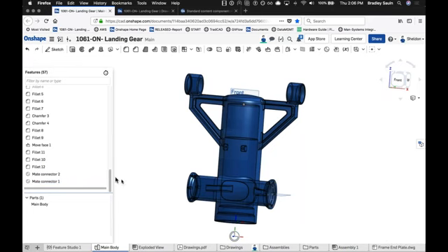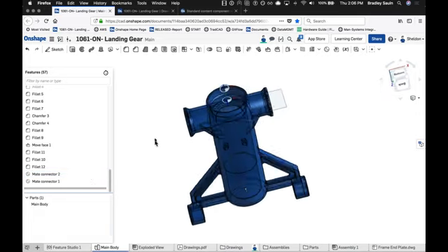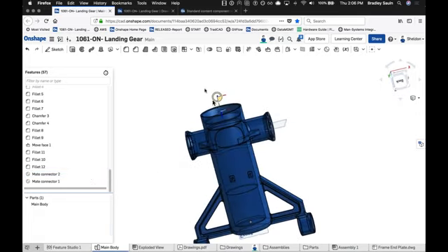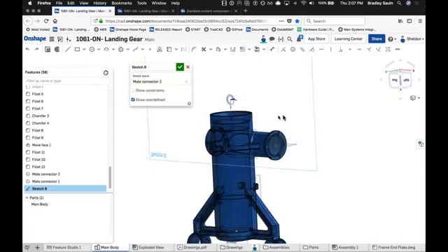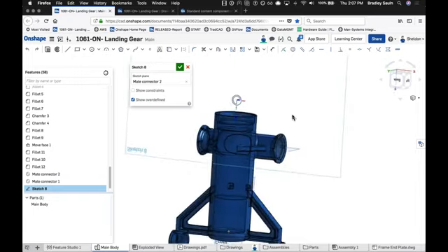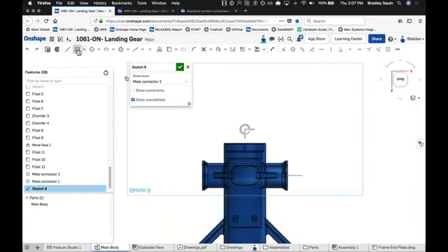Along with these make connectors that I've reordered, we can also now reference make connectors for a lot of things in the design side. So we tend to think of make connectors as very useful in the assembly side of things. You'll notice in Onshape, right, there are no planes in the assembly. So we've now opened up the functionality for make connectors in the part design side of things, where we can reference them both for sketching. So I can actually use this as a sketch plane now, where I can select it, hit Shift S to start a new sketch command, and I now have a sketch plane in line with that make connector point. And let's just say I want to draw some sort of profile, maybe to revolve.